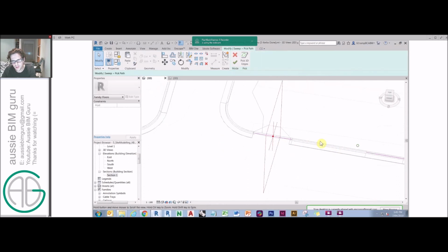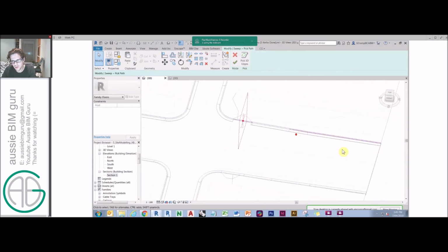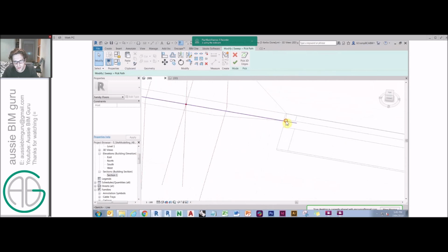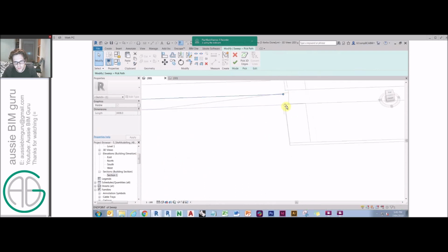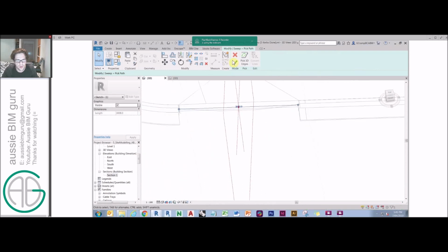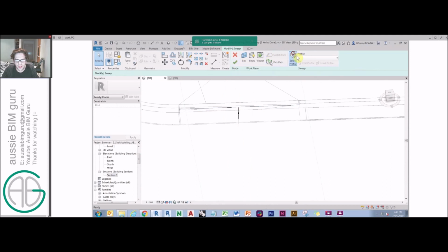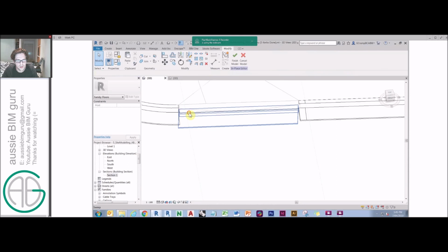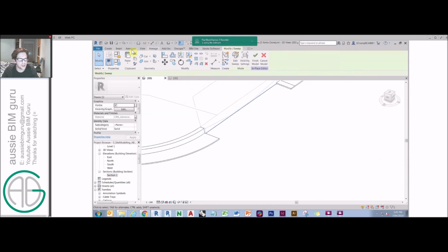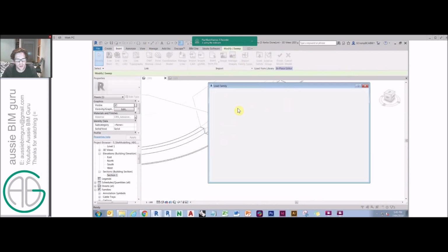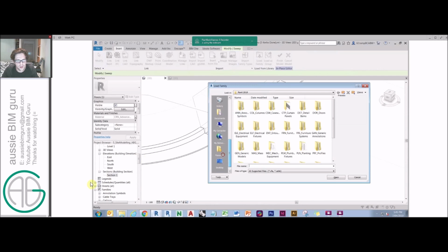What I've actually done at this stage is I've built a special profile, which is basically the curb profile without the upstand to meet the curb, so the curb ramp will essentially come down to it. You should usually get some snaps on these. I'm being a little bit rough with how I'm doing this, so I actually need to load in the profile for this bit. At the moment this is just automatically rotated, so I'll go and load it in here.